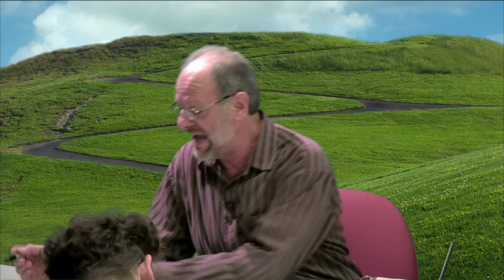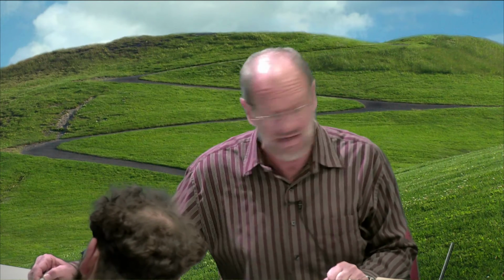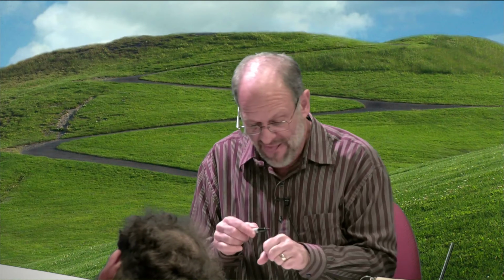For polytropic, how do you know it's polytropic? Okay, good question. I like to think of polytropic processes as kind of a catch-all. Keep in mind that when you're dealing with a polytropic process, it really just tells you that the relationship between pressure and volume is a continuous polynomial function. We go from point 1 to 2 following any of a number of lines, and as long as it's continuous in this fashion, then there will be some exponent n and some constant c that would give you the exact equation, or at least pretty close to the exact equation, for the actual process that takes place.